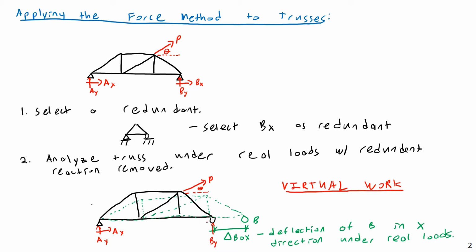And once this is able to move, you turn this pin support here into a roller support, this thing will just freely deform under force P, and you can just calculate that deformation just like you would any virtual work problem.